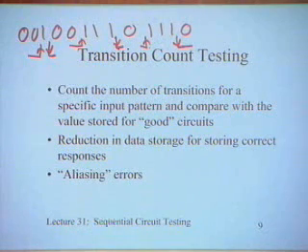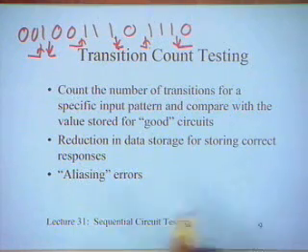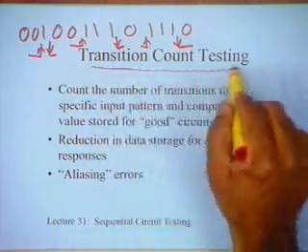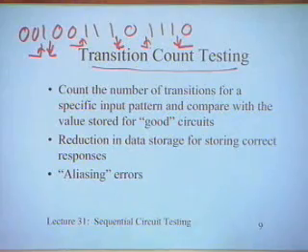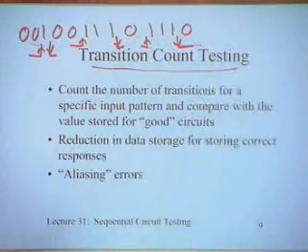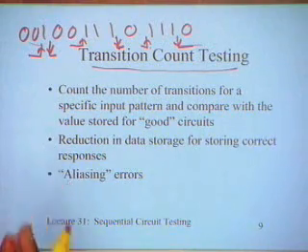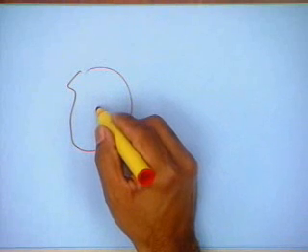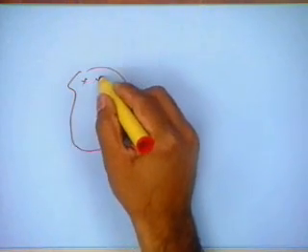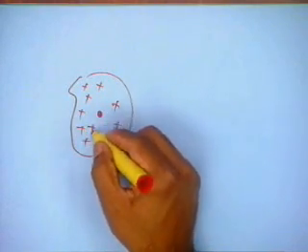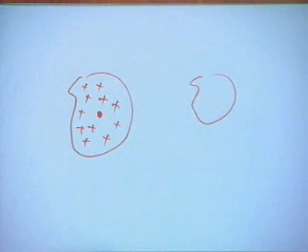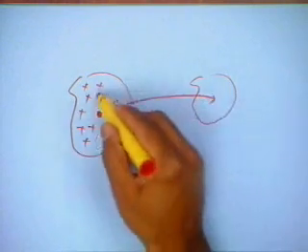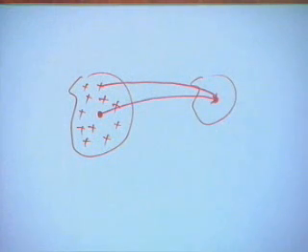But please remember one thing about all these techniques that we are talking of; later on we will talk of some other techniques for signature analysis. When you start doing such things, the result vector is being reduced. There is a result vector that you wanted, and you are compressing it into a fewer number of bits. So this is the space of the result vector. There is only one of them which was actually the correct result vector, the correct pattern, and all the others were wrong. Now I have a compressed result vector. When I take a compressed result vector, multiple results are going to map onto this.